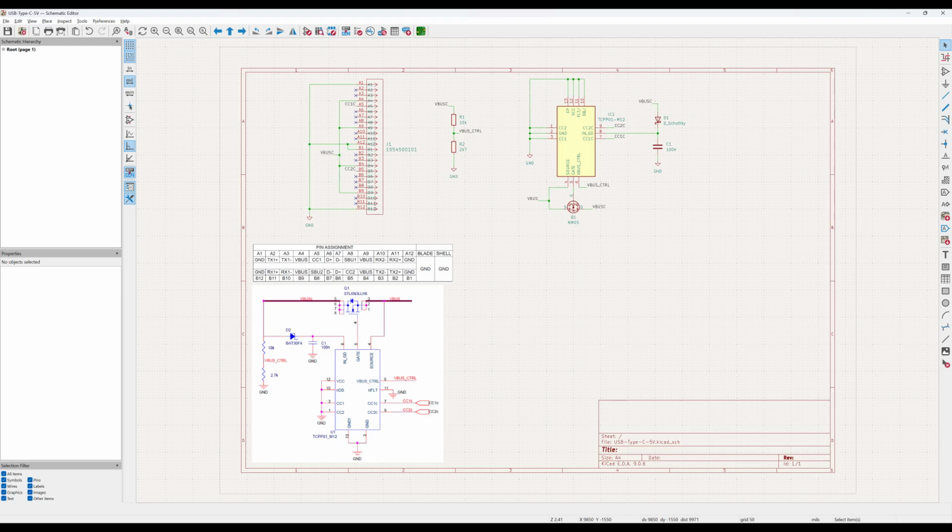It appears we've implemented the functionality we wanted, so, can we move on to PCB layout? No, we cannot, for several reasons. First, we have not specified the exact components for Q1, D1, R1, R2, and C1, and, consequently, these symbols do not have an associated PCB footprint.